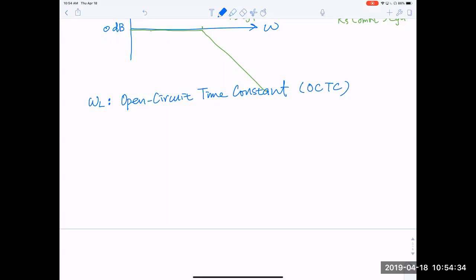So what is this method? Well, it's the same small signal replacement: voltage source, short circuit; current source, open circuit. These are all standard now. But how we consider capacitance, we also do capacitance one at a time.